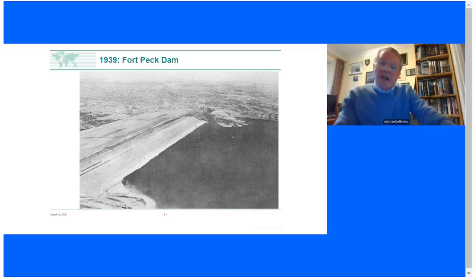But more or less concurrent with the Franklin Falls Dam, they were also building another dam up in Fort Peck, which is up in northeast Montana near the Canadian border. And that dam is another hydraulic fill dam, and that also had a flow slide, which is what you see on this photograph here. This is an aerial photograph from the day. And when you see this case history written up in the literature, you think the whole dam failed. Well, no, it wasn't the whole dam. It was just a length of the dam out near the abutment.